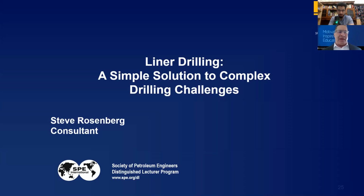One thing I didn't mention, I'm sorry about this, it is compatible with managed pressure drilling and also continuous flow systems. Why is it compatible with managed pressure drilling? Because the drill pipe itself is connected to the surface, so you're sealing around the drill pipe. Liner drilling has been used very successfully with managed pressure drilling.